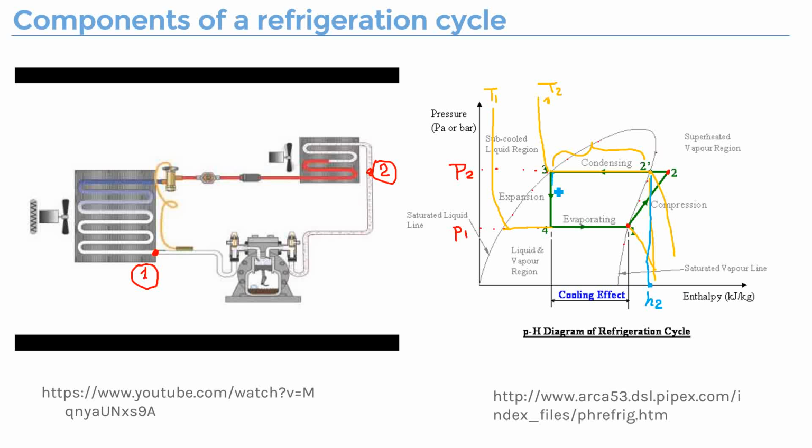And for the other point 3, you also draw a vertical line, and that is H3. So I would say the enthalpy change between point 3 and point 2 would simply be H2 minus H3. All those things you can find from the table or those charts. And here, this delta H.